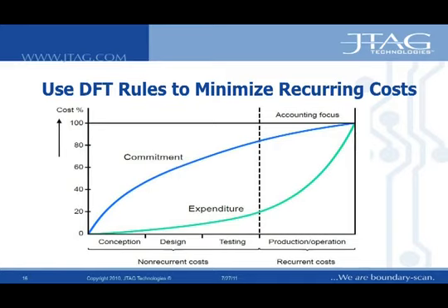The amount of recurring test costs during production depends on the testability of a board and hence is already determined during its design. Boundary scan provides an excellent opportunity to limit the recurring test costs of a printed circuit board. By taking a few simple design for test rules into account, different test and programming applications can easily be created and can be used efficiently in manufacturing as well as field service. Closely watching the testability of your design and fault coverage of your tests not only limits those test costs, but also helps to get products to market faster with higher quality levels.